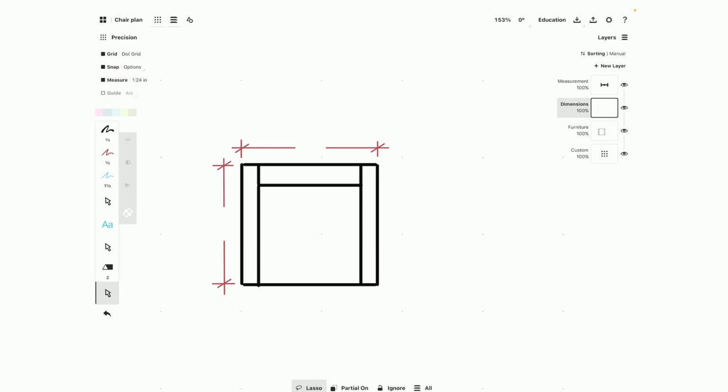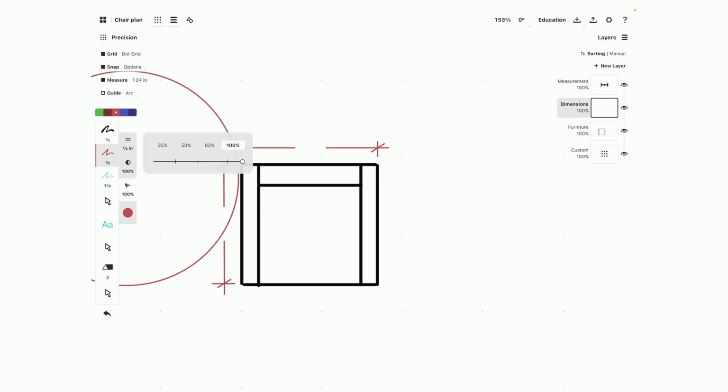My dimension strings are a little exaggerated for this drawing, not much, but it's definitely here for you to make sure that you can see them. At this point, we can draft in or write in our measurements. I'm going to stay on my dimension layer, and I'm going to just use my freehand text. To do that, I'm going to bring my smoothness down to 0 or 2%. You want to bring it down low so that you can now draft and write in text freehanded.